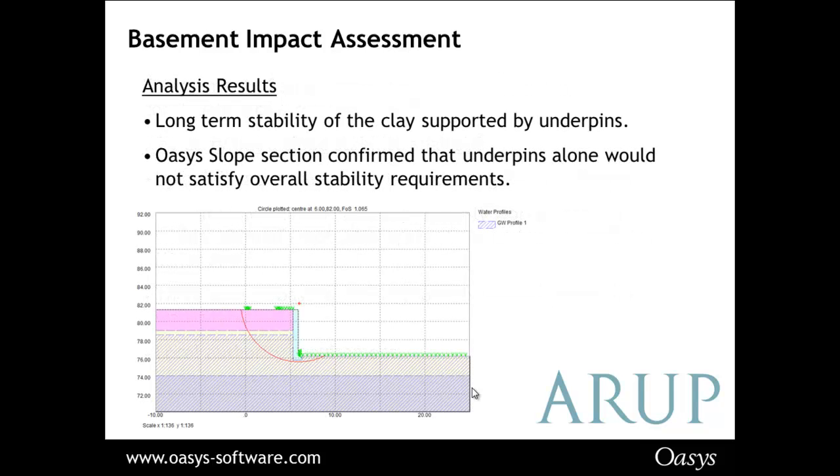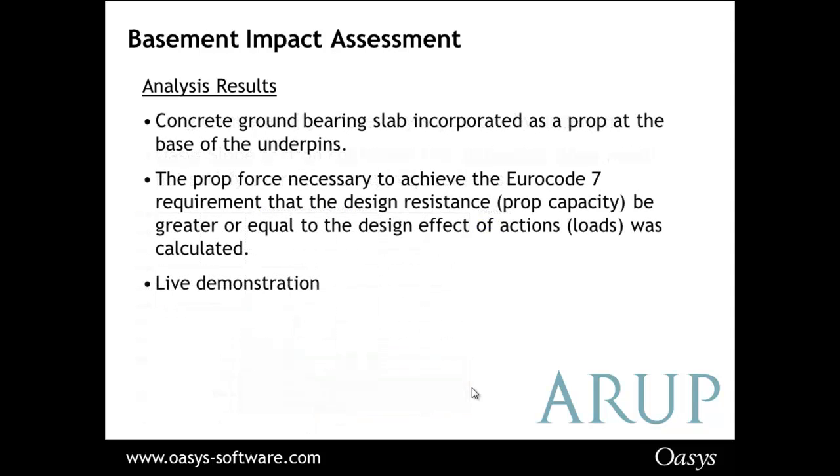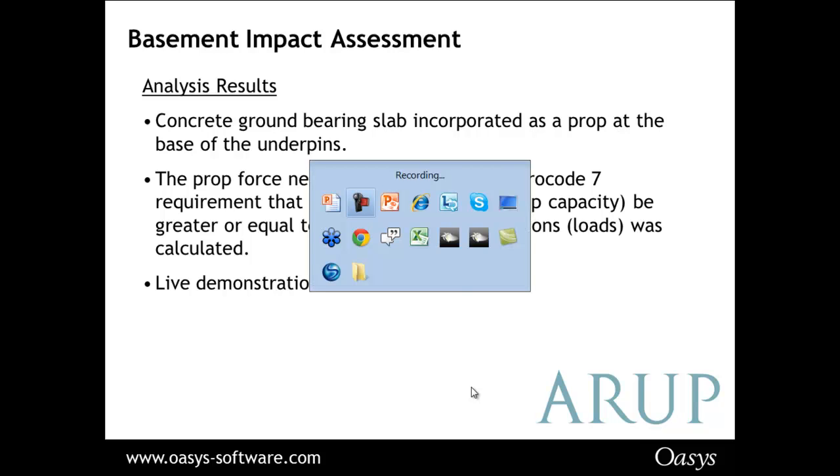So with all this, the Arup engineers ran a long-term stability analysis of the clay, which was supported by underpins. Oasys Slope analysis confirmed that the underpins alone would not satisfy the overall stability requirements. So for this particular analysis, what was done is that the engineers carried out a Eurocode 7 factored analysis, and they stated that the concrete ground-bearing slab could be incorporated as a prop at the base of the underpins. So if I go into this analysis,